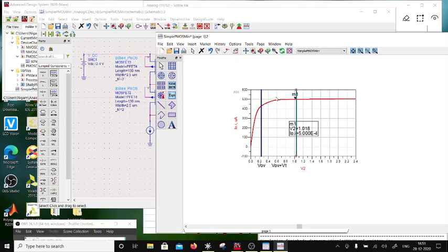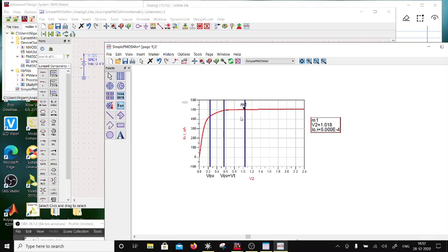But also notice that you have moved from here to here. So the net voltage on V2 cannot go below this. If it goes below this value, so what is that value? That value is twice of V overdrive plus Vt, twice of V overdrive plus Vt. Now I'll tell you how that is. Let me see if it is correct.